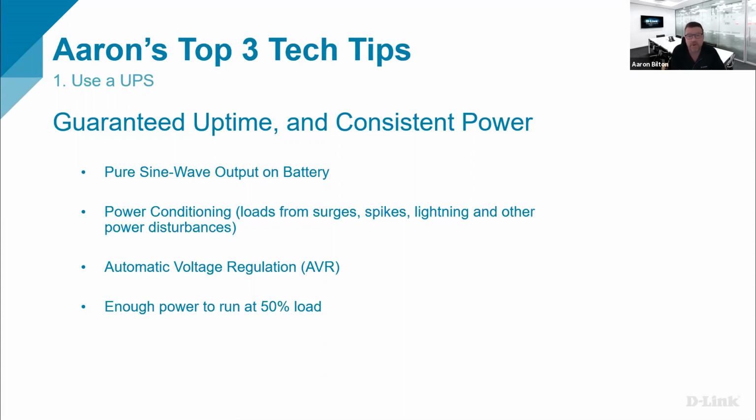If you are putting a UPS in, first of all, make sure it's a pure sine wave one. If you have a cheaper one that's putting out a pseudo sine wave, which is more of a square wave, anything that's running a plug pack power supply, that switch mode, may not like the output, and they may squeal or fail.